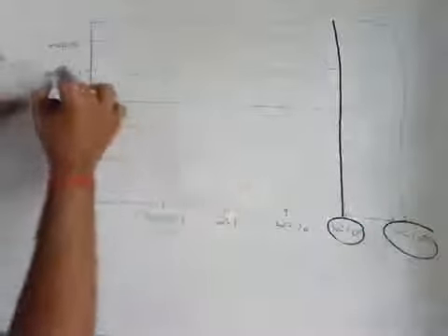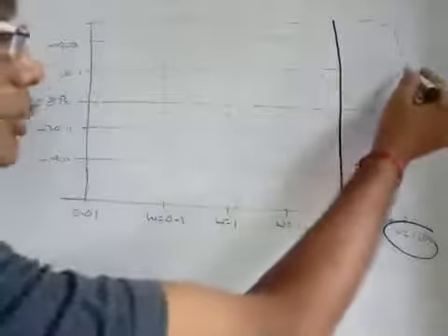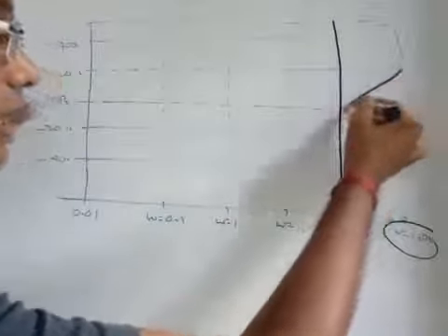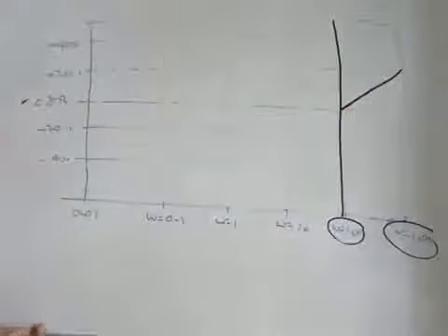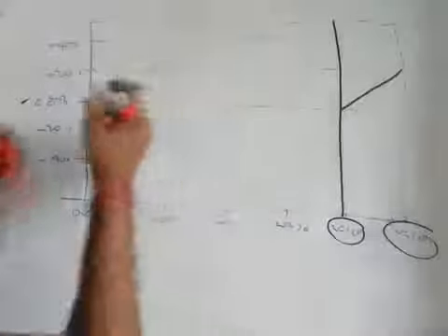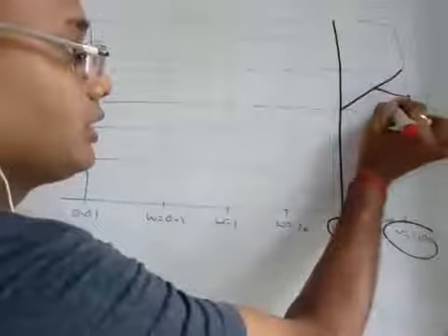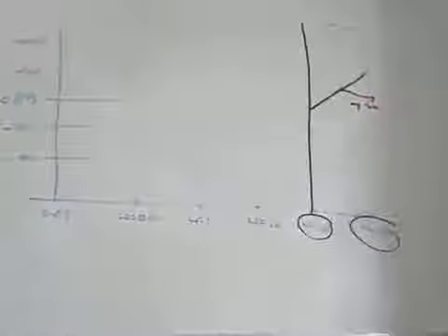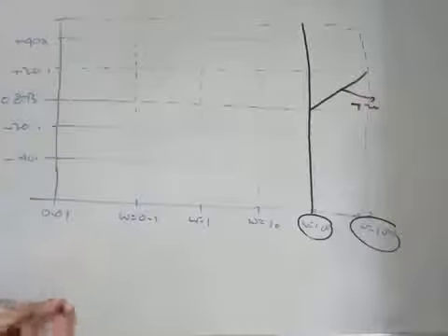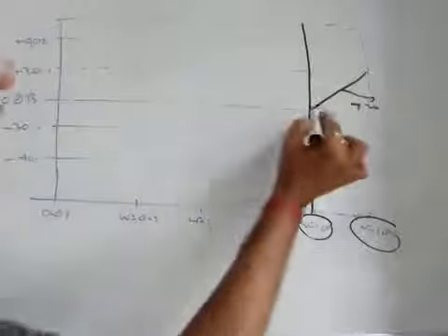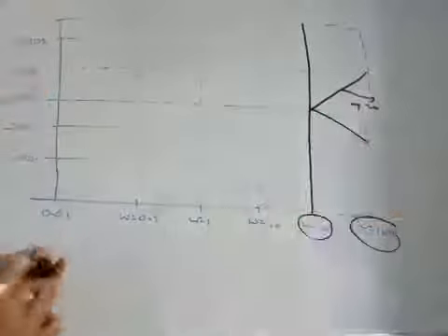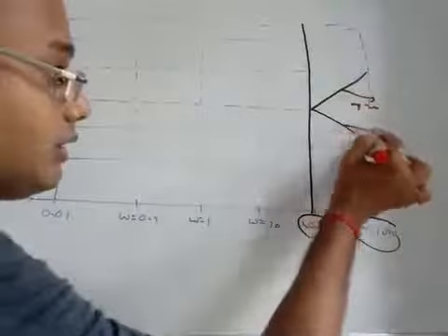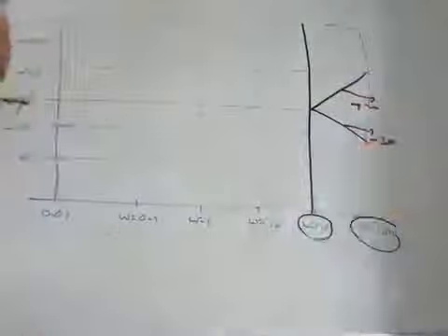Now say 0 dB to plus 20 dB. So magnitude to this, and if you draw this line, what is the slope? This slope you can write as plus 20 dB per decade, right? And similarly, if you draw from 0 to minus 20 dB, this is your minus 20 dB line.